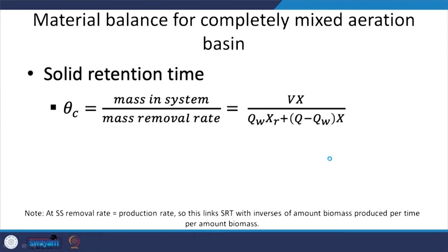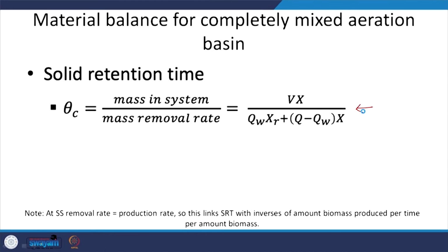So, let us try to combine those two aspects. Okay, before I go further, let us look at this under system and try to understand that. Suspended solid at steady state removal rate equal to production rate, right. So, this links the solids retention time with the inverse of biomass produced per time per amount of biomass.